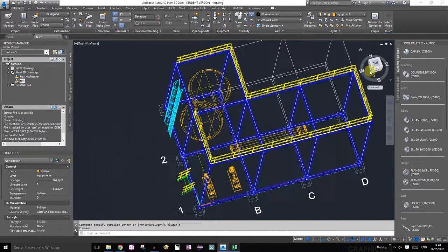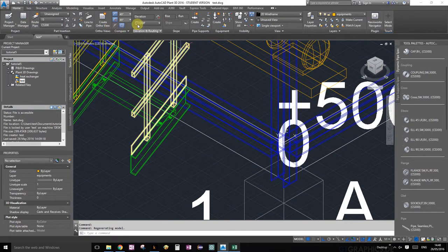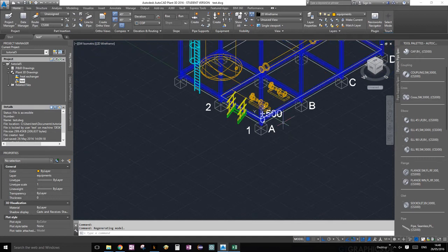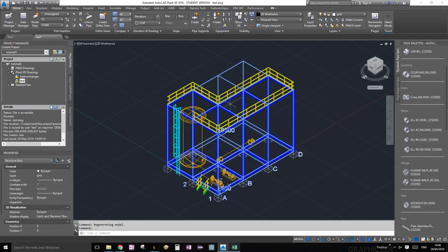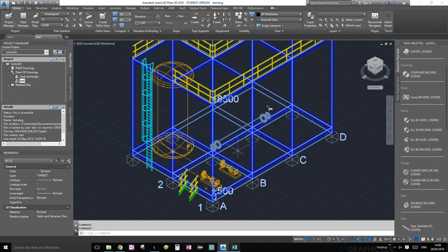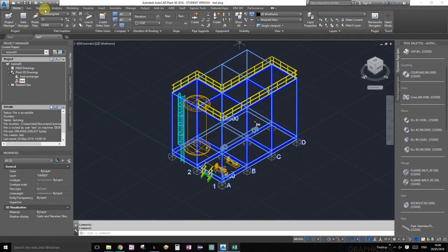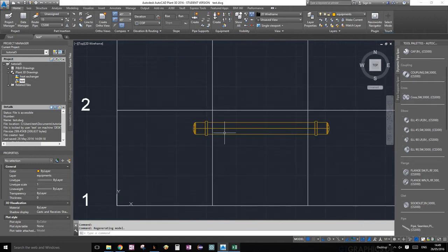Another thing I forgot is to make sure that our user defined coordinate system is exactly on top of this first platform. To do that, we should restrict our views first. Let's choose the grid and our heat exchanger and hide everything else. From the home ribbon, go to the visibility palette and click on hide others. Perfect. Let's go back to top view. Now we can see.